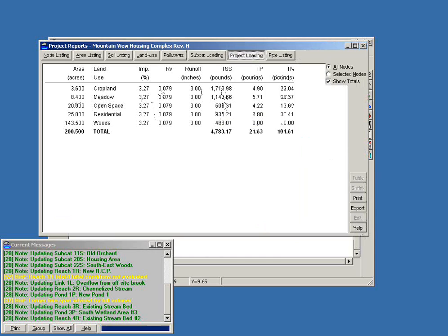There are a number of different techniques for calculating the imperviousness, and that's one of the things you'll want to look at in the HELP system. You'll need to study your regulations specifically to see how you want to use that. The simple method is one of the techniques that's available, which calculates the loading based on imperviousness, but you also have the option to calculate the pollutant loading on an individual event basis, to have HydroCAD use the actual rainfall that is being calculated, such as with the SCS method, and use that to do your loading. So you have those and other options available to you. So this is just to let you know that those loading calculations are available to you in HydroCAD.